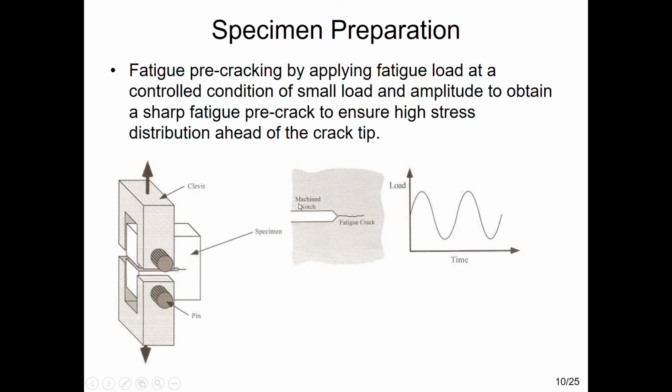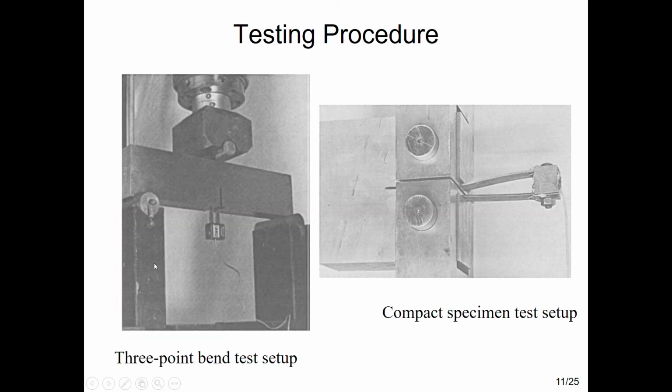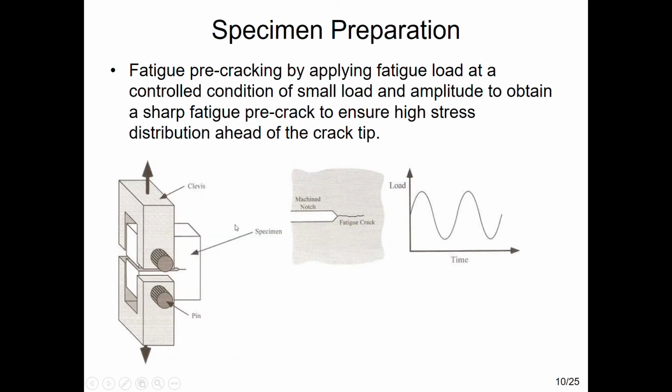You can see I have the machined notch here, and then the fatigue crack is here. From here, they also apply the load where it will be an open crack opening mode. Only by doing this, you actually can see how the load varies along with the increment of time. Because we are talking about fatigue, fatigue is actually dependent on time.